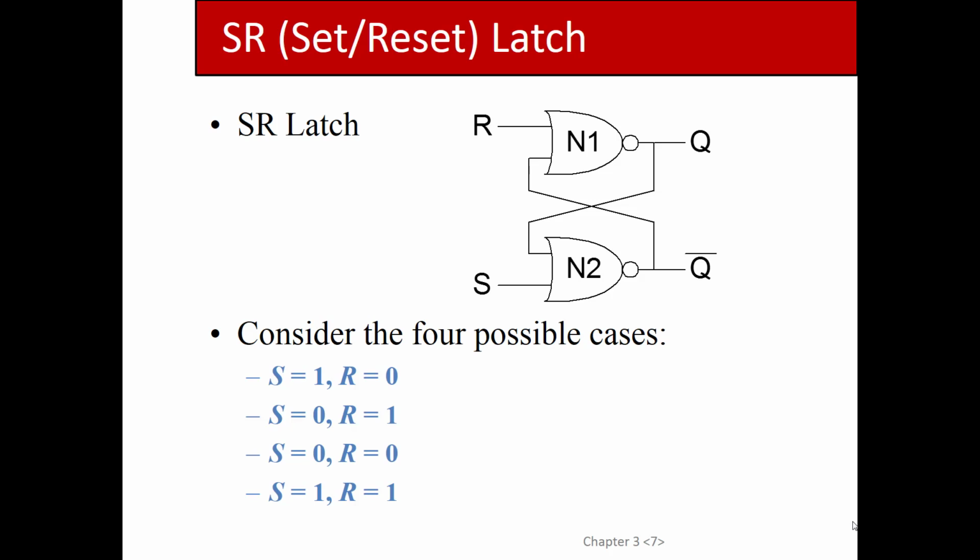If you put a 1 into a NOR gate, it's the same thing as an OR gate, except you're guaranteeing a 0 is going to come out. So the idea is that if I put a 1 into R, then Q is already determined, it's definitely going to be a 0.